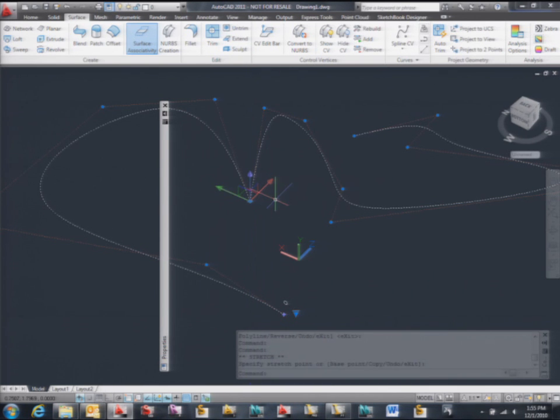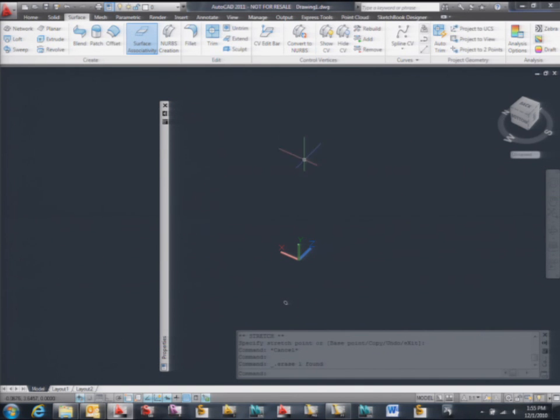A kink is a point where the continuity is lost, right? Normally the spline will always have C2 continuity all across the spline, but we now managed to create a point of lack of continuity within the spline. Depending what you do, this may be very, very useful, right? And there was no way to do that before.